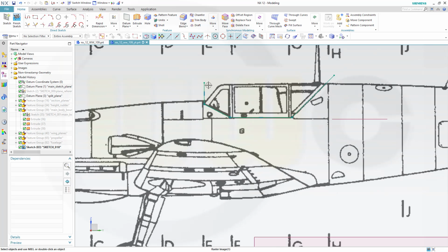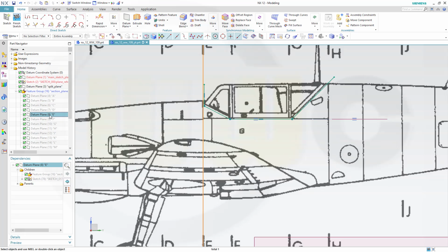So this should be coincident with the E-plane, this one with that plane, yeah. So let's add some constraints. This one and that one should be collinear. And this one should be collinear with the E-plane. Where is my E-plane? Let's go for the E-plane, this one, and that one should be collinear as well. Yeah, that should do.